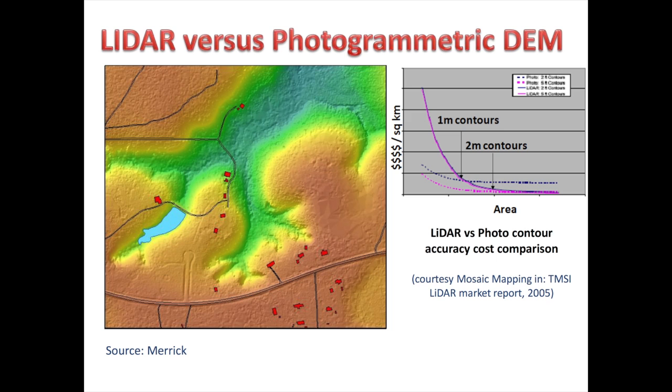With LiDAR, of course, because it's an active illumination technology, we can capture far more points beneath the canopy and generate a much higher resolution DEM. So in essence, that's one of the values of LiDAR over traditional photogrammetric methods for DEM generation.